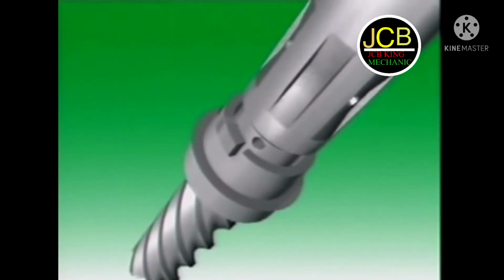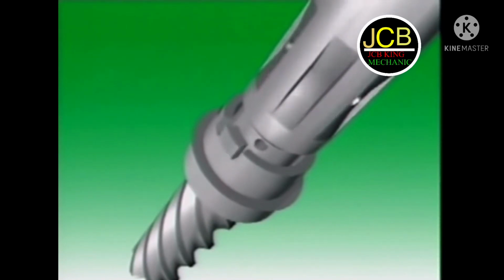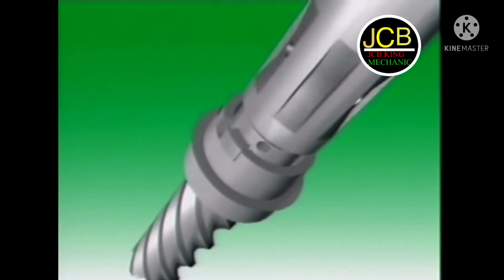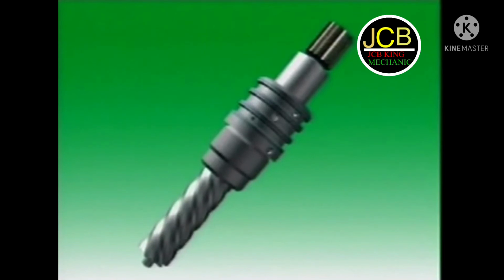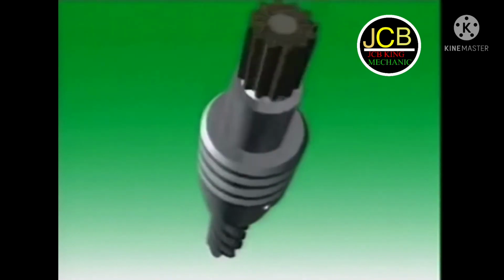The input shaft can twist through only a small angle before it contacts a stop on the pinion gear. This is needed to provide manual steering when power assistance is not available. With the engine running and the steering in the neutral position, fluid flow is directed into the valve assembly through drilled holes in the outer sleeve.